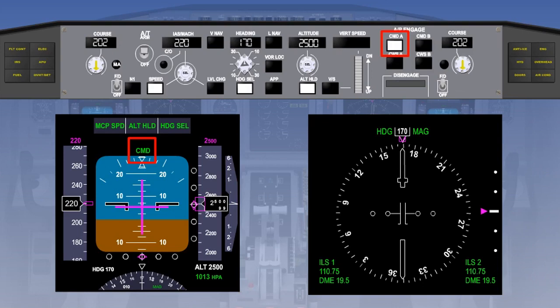be provided with radar vectors and descent heights to intercept the final approach course. The aeroplane would normally be set up under the control of a single autopilot, with the auto throttle controlling the mode control panel indicated airspeed. The crew will select the flaps and gear as appropriate to the aircraft during the approach. The autopilot will not select flaps or gear.